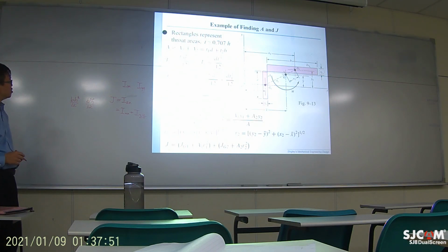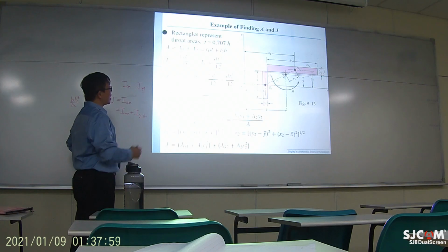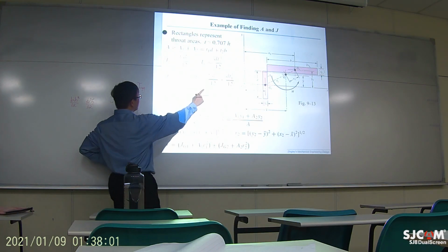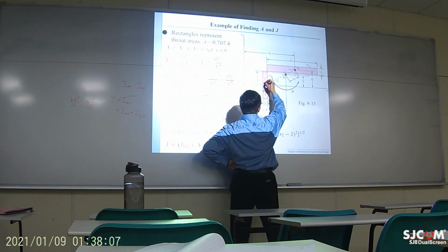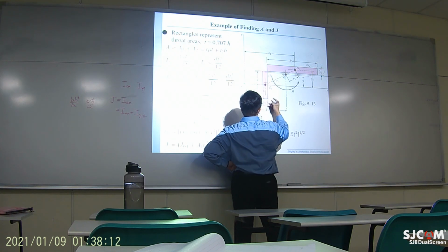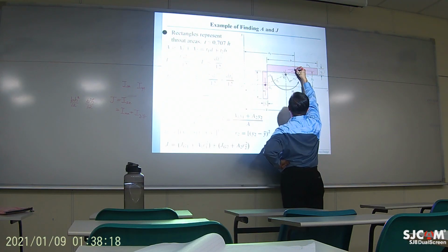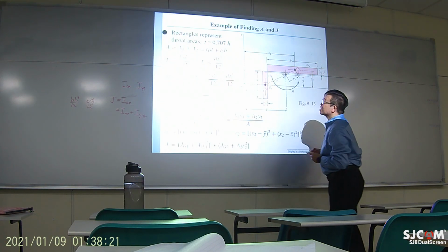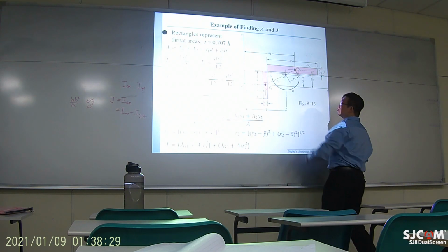These are the two equations for Ixx and Iyy, so that's why you will see these two equations right there, and that's how you compute J. And here, it computes JG1, so it's the J of the first area at the G1 point. And it also computes the J at this point, JG2. So that's the polar moment of inertia about the centers G1 and G2.